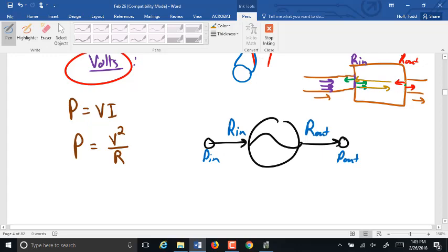It's hard to explain, but if the input and output resistance are balanced, you can capture those reflected signals in there and wipe them out. If they're not balanced, they go back and forth, and some of them leak through, and it gives that kind of an echo effect, whatever your signal is, and that's very, very bad.